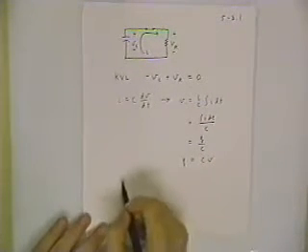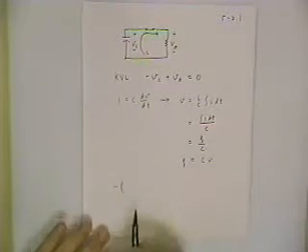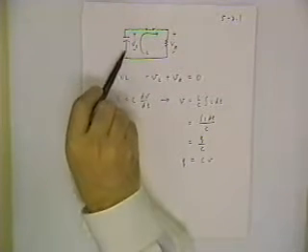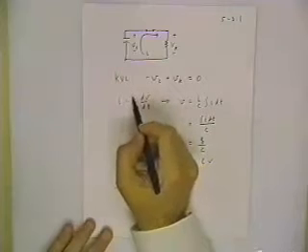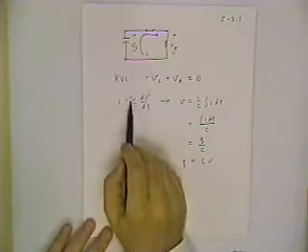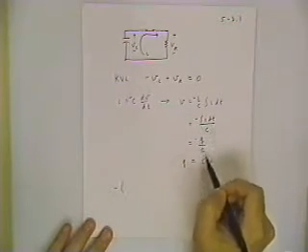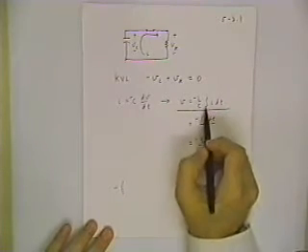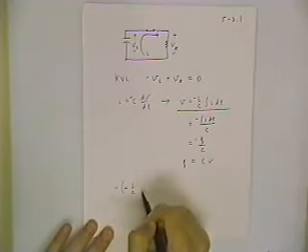So if we continue with our Kirchhoff voltage law, we have a minus VC, but remember the passive sign convention? This current is going from lower to higher potential. And the way I wrote the model here was with the positive sign. If I wanted to make this correct with the passive sign convention, I need a negative sign here and a negative sign throughout here. And so for purposes of substituting into our equation, this is what I need for the voltage expression for the capacitor, and there's the crucial minus sign.